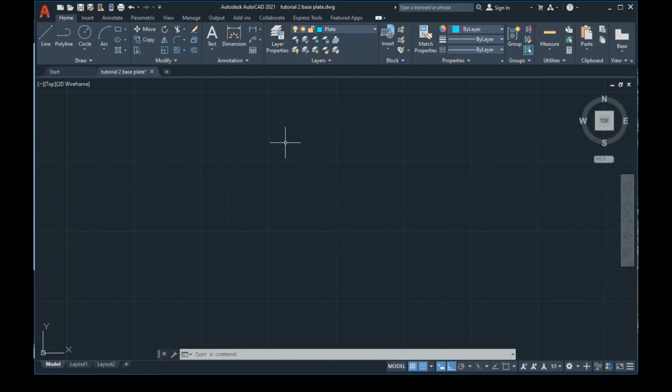Fine. So let's start with the line command. The line command comes with L. We have an option of the line command over here also, but we'll do it with L. First I'll press L and click enter. As soon as it says specify the first point, I'll write 68,7 and press enter. So look, I've got my first point. Fine, this is my point 68,7.